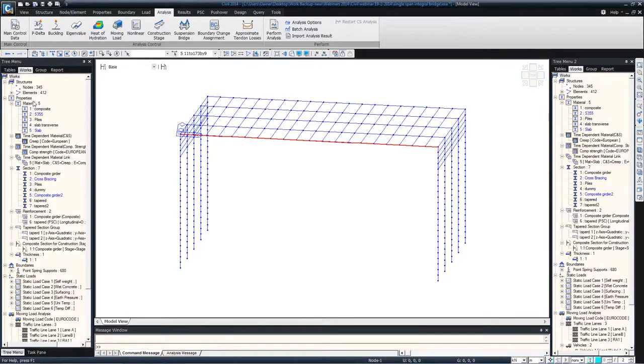We have another question related to the live loads. The question is: does it matter which reference beam we use as our starting basis for defining our lanes? It does not matter as long as you have defined the crossbeam type of distribution. You can use some other lane and define some different eccentricity to match the correct position of the lanes. So as long as you have defined the transverse information that you want to apply the loads via the cross beams, it gives you the same results for any reference beam.